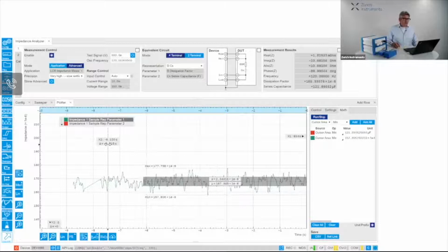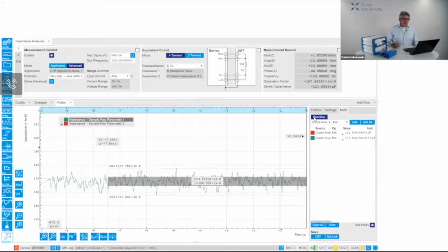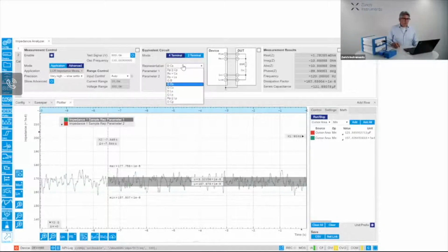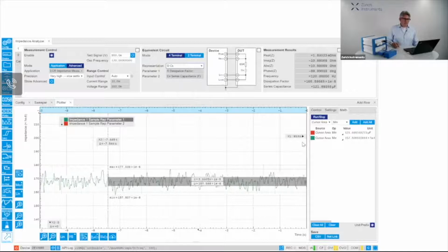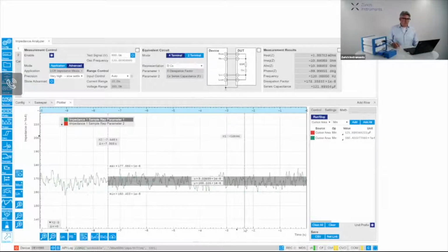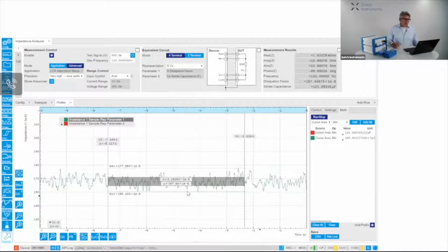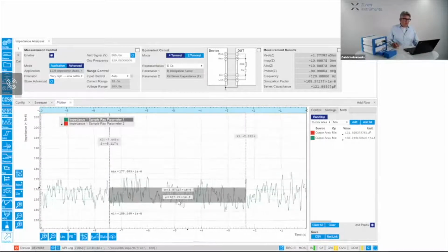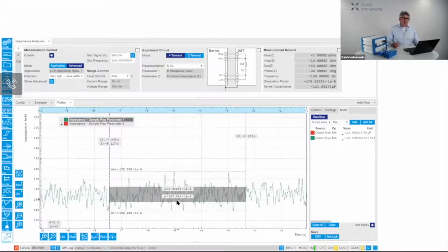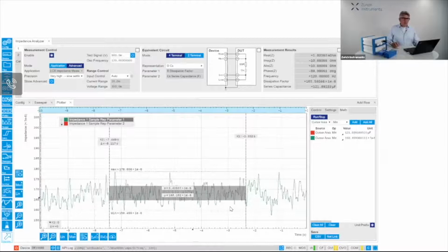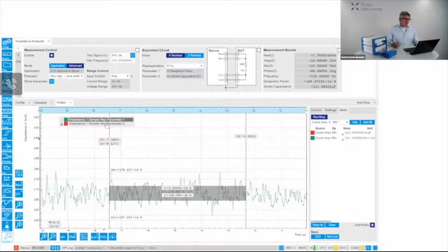So here we see the green line. This is the tan delta because from the drop-down menu, we've selected delta and series capacitance. So let's measure this using a math tool, cursor area. You can see here that the measurement at 120 is 1.6 times 10 to the minus 4. So that's well within spec of the spec sheet of this component.